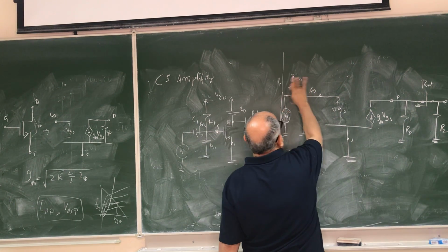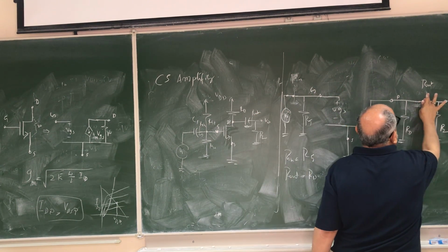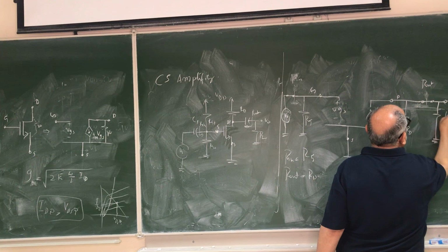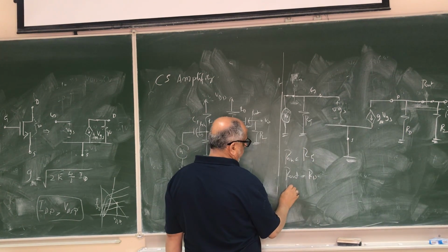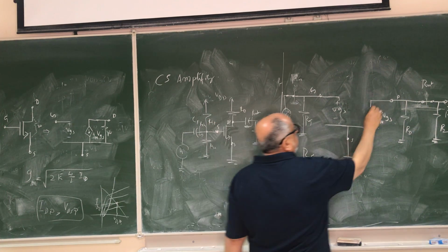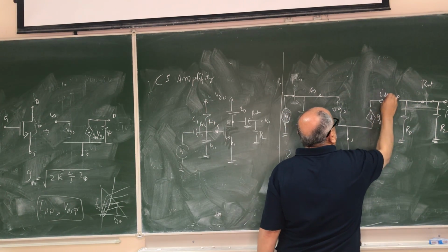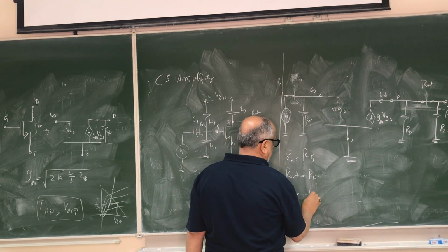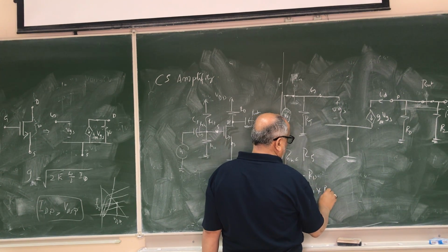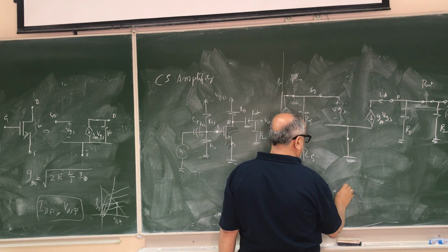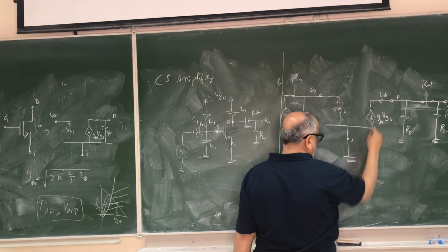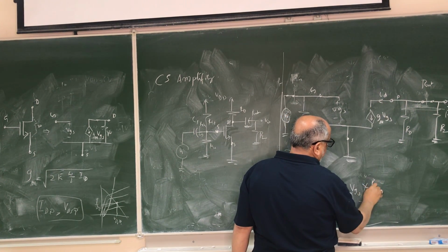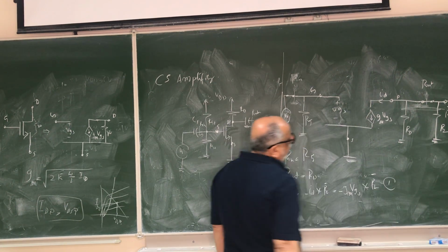Now finally we have to find the gain. Also forget about this now. So we have to find the gain now. I can combine these two resistors, I call them RL dash as we've done before. So we can say V out is equal to, this current is ID, right? V out equal to minus ID into RL dash equal to minus GM VGS, because it is the same, right? Multiplied by RL dash, and this is my equation number 1.